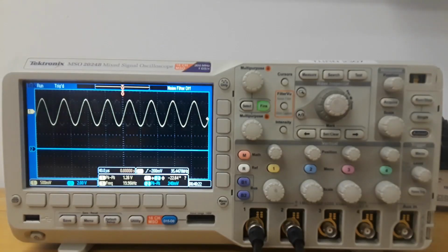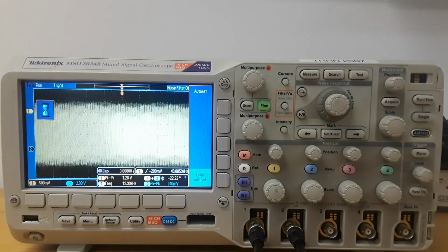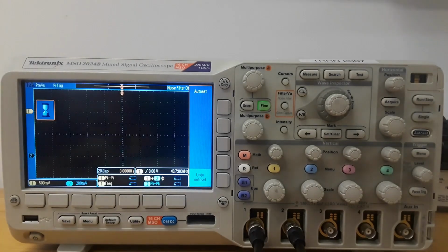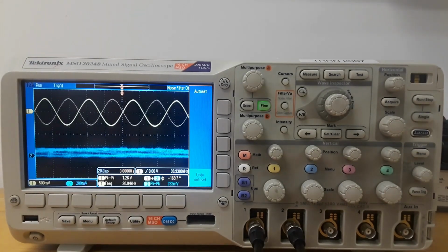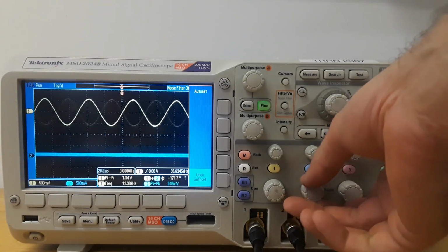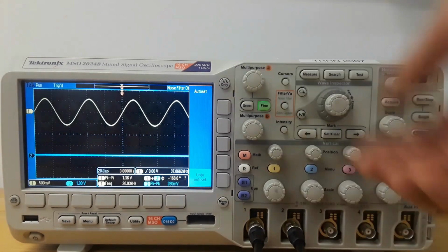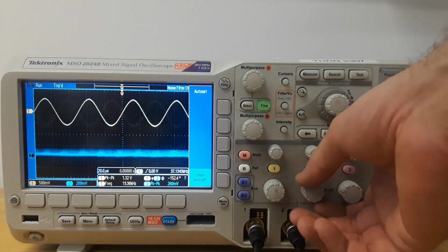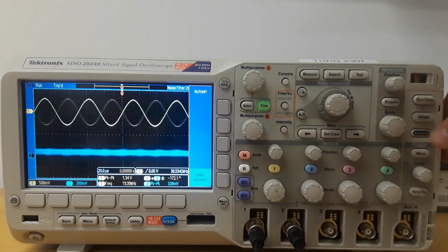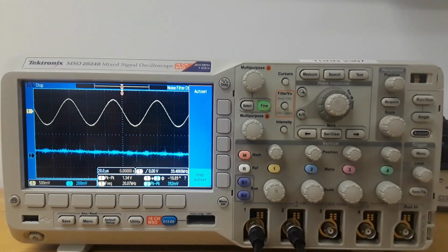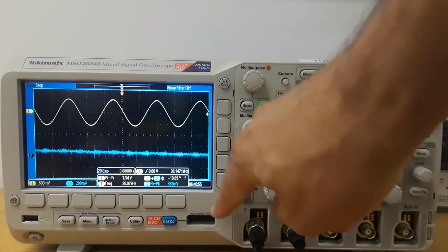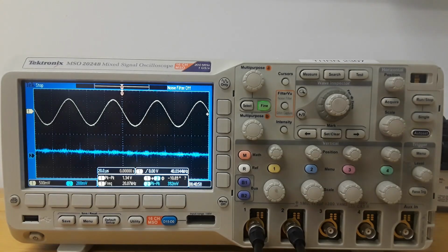Now here is the oscilloscope, and on the oscilloscope you can see that the sine wave is currently visible. We're going to press auto set here just to see what comes up and if we can get a clearer picture of that waveform. And we can get a fairly clear picture of the yellow waveform. That's channel 1, the input, and the output is telling us nothing more than noise. If we zoom in with the vertical scale on the knob here, we can see it's a lot of noise. If we hit single, we can see one particular snapshot of the noise there. Turn that menu off. Or we can let it run.